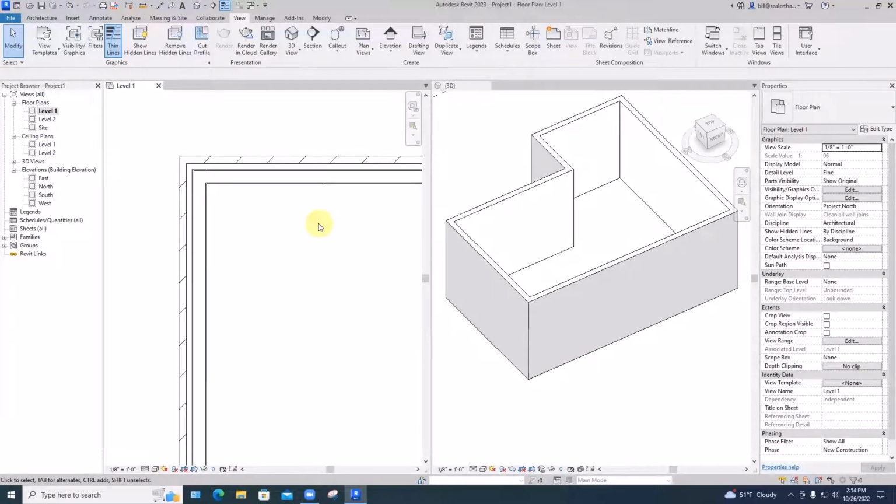The reason to be able to show different levels of detail is that when you're doing a wall on an 1/8" plan and your wall's about this thick, if you have all those lines in there, it's just going to be a totally blobbed out solid wall. So at that point, you kick it back down to either a medium or a coarse view and just show the outlines of the wall. And then in a detail view, or where it's important, where trim or something goes, at a larger scale, you can use finer detail.